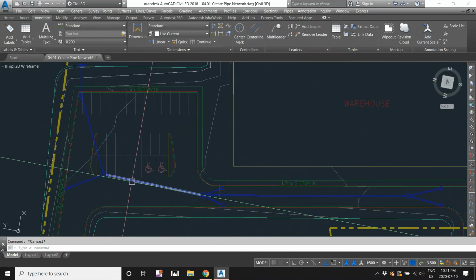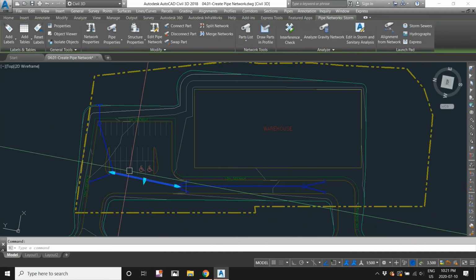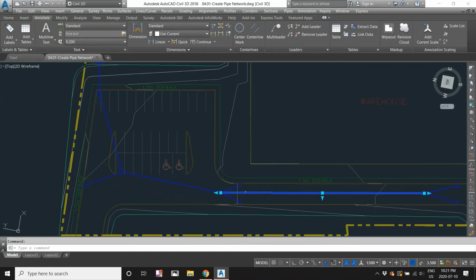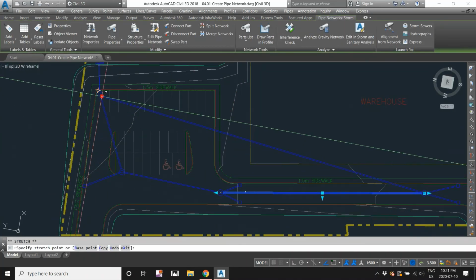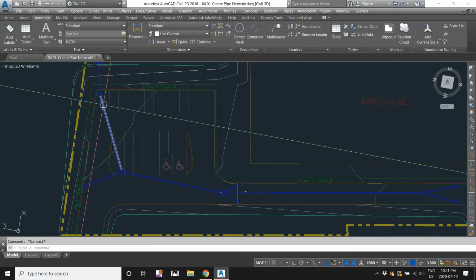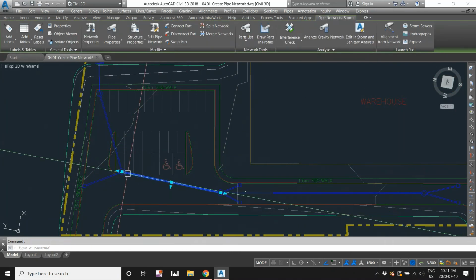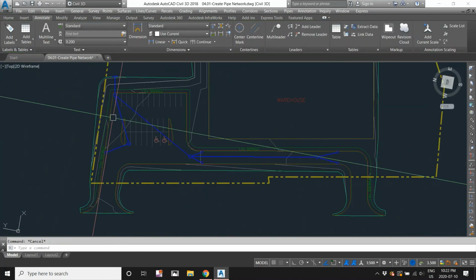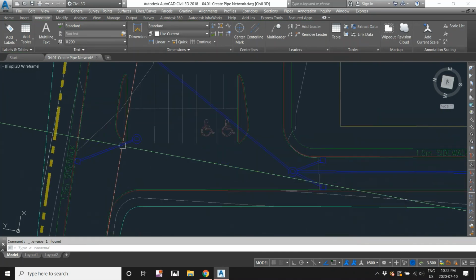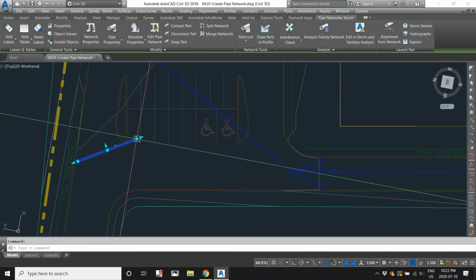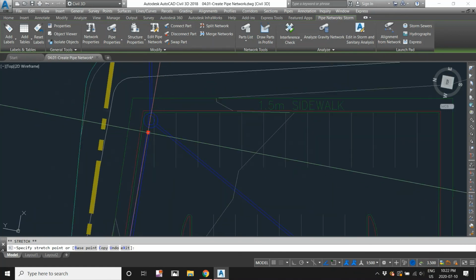Remember, you need a manhole, for example, the whole point of a manhole is so you're allowing this pipe to turn around here. But maybe you have a better design. Maybe you feel we can connect this pipe to here and delete these two, that additional manhole structure.